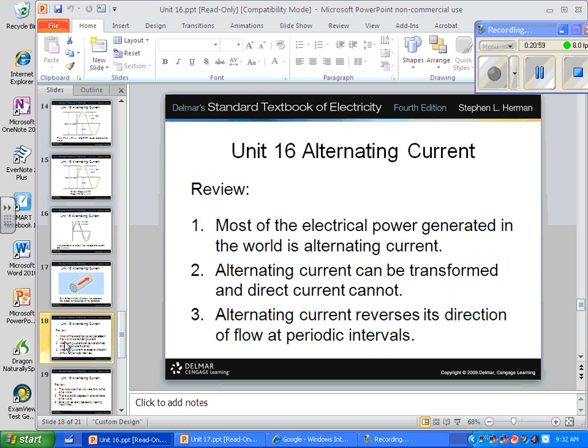They want to be able to transmit as much power as possible with as little voltage drop. The higher the current, the more the drop, and also the L in our formula, length, from Arizona to here, we cannot change, can we? The only thing we can change then is the current. And the only way we can change that is take that same amount of power and use a higher voltage. And the current is a proportion of that, because remember our formula about power, right?